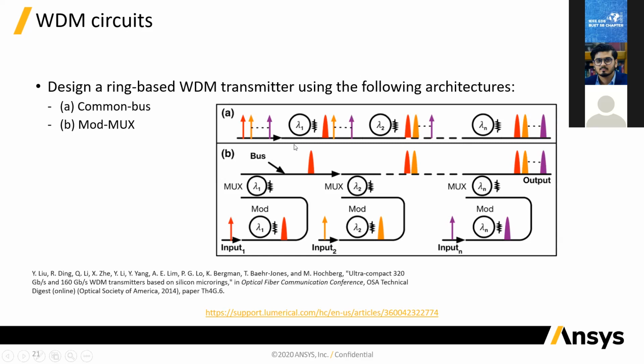So here, for example, you have multiple channels. One option would be that the signal propagates on a waveguide, and you connect 3 different ring resonators in series with that, each of them tuned for a particular wavelength. Then you apply a modulating signal to each of those modulators to encode your electrical signal on top of the different optical signals, one wavelength at a time.